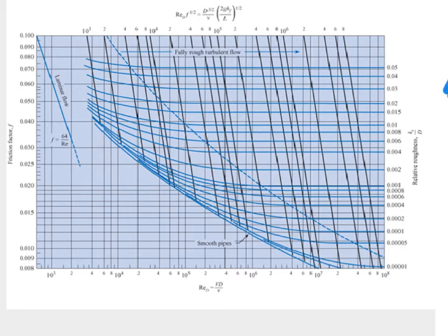we have a relative roughness over here. Epsilon equals Ks on D. And we have a Reynolds number over here. Reynolds number equals Vd on nu. We can't get the Reynolds number. We can get this epsilon, because we know Ks, or we should know it because they gave us that it was a clean concrete pipe. We'll go back and look at that, and we know the diameter. So the diameter is 0.15 meters, and the Ks is going to depend on the material.